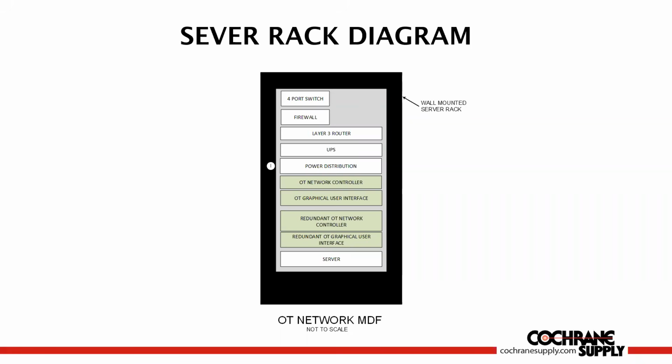You're responsible for looking at that hardware, determining the size of it, and getting a cabinet that accommodates all that hardware, right? And the good thing about it is that as an engineer, you can look at this early on, and let's just say this is a 10U cabinet. Well, you may want to go and look at the cut sheet for a 12U cabinet and tell the architect, this is how much space that I need, and here's how much it weighs, right? If a 10U cabinet is selected and it can accommodate everything, then you're doing great. It's a little smaller, it's a little lighter.